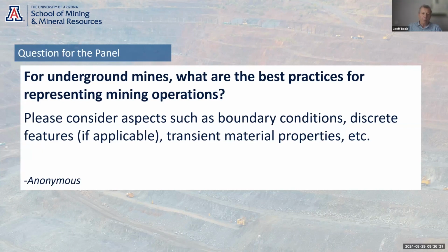So we implemented a program 20 years ago of mining towards the exploration drill holes and pressure grouting the formation close to, and trying to frack the formation and drive cement and cement the exploration drill holes, which we were able to do successfully, and they've been doing it ever since 20 years later.